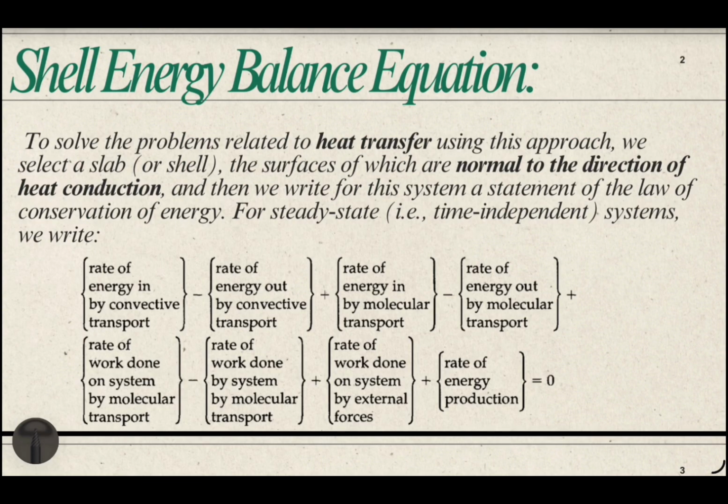Whenever any heat transfer problem is given, we can solve it by the shell energy approach. In this approach, first we select a slab or element, which is also called a shell. The shell should be normal to the direction of heat conduction. And then we write the following equation. This equation is nothing but conservation of energy.